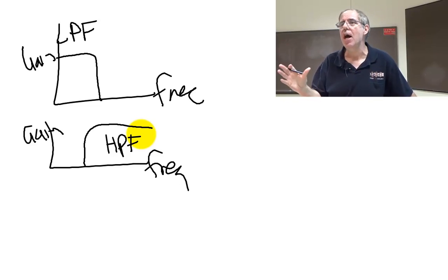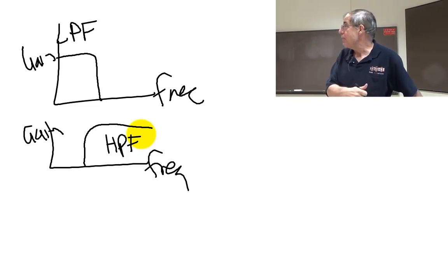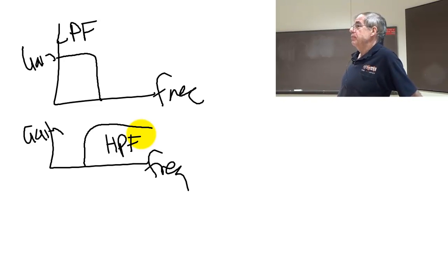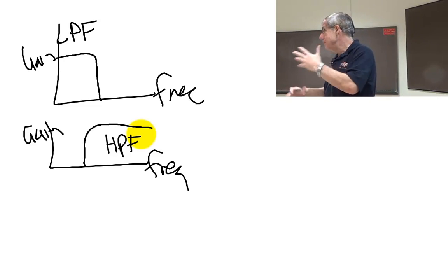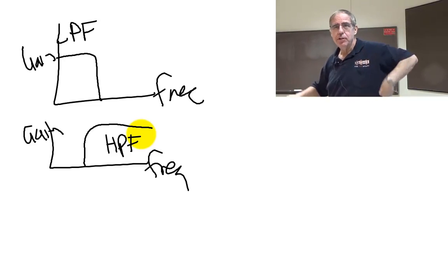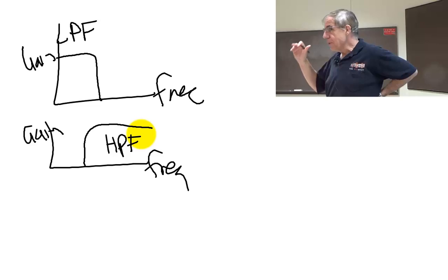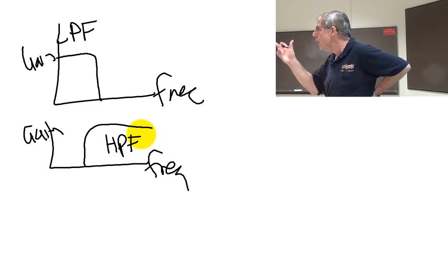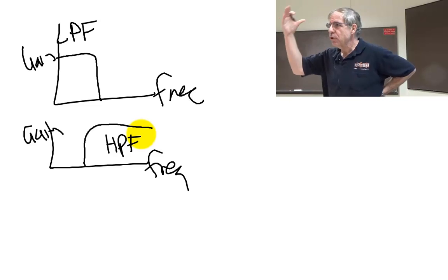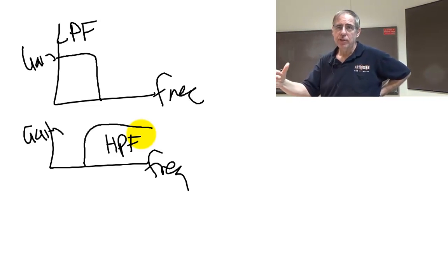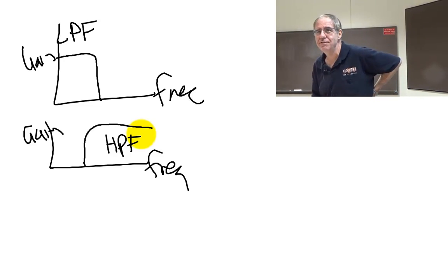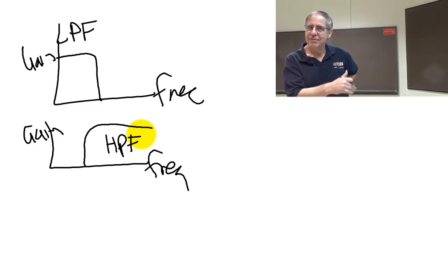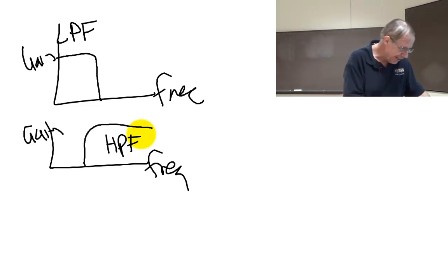Now, if you go to Lab 9 and you're measuring temperature and you use a high-pass filter, we're gonna laugh at you. Just saying. Trying to measure temperature in this room, right? It's 75 degrees, the perfect temperature, Fahrenheit. I'm going to laugh at you if you use a high-pass filter. Why? You just threw away the data and just kept the noise. Right? That's a noise to signal improver. Right? Be careful. Thinking is required, okay?